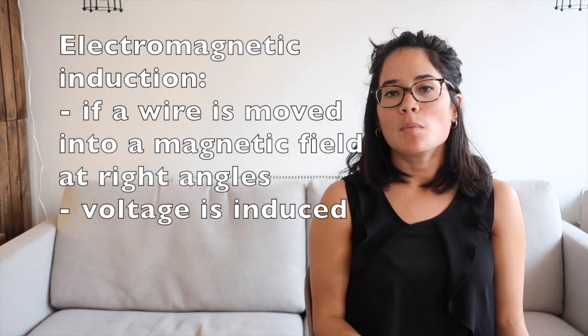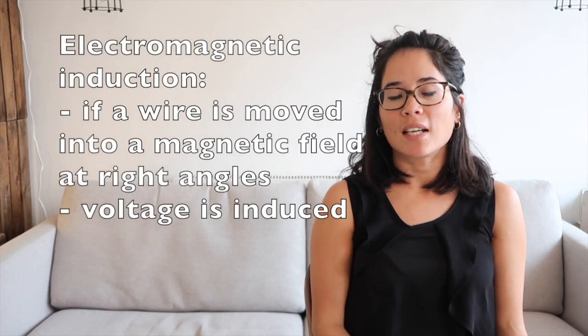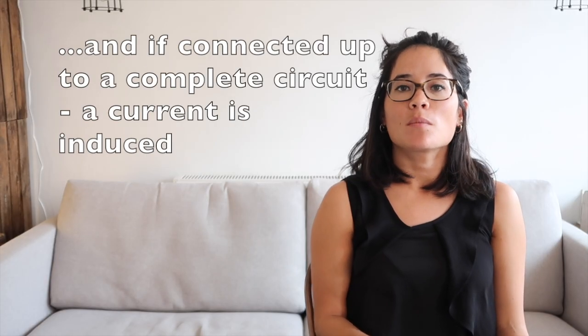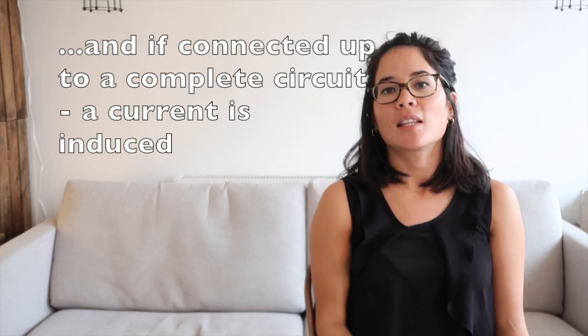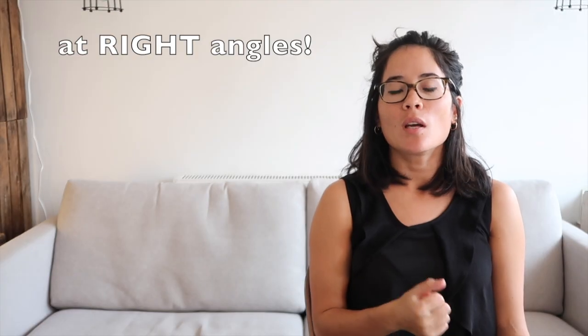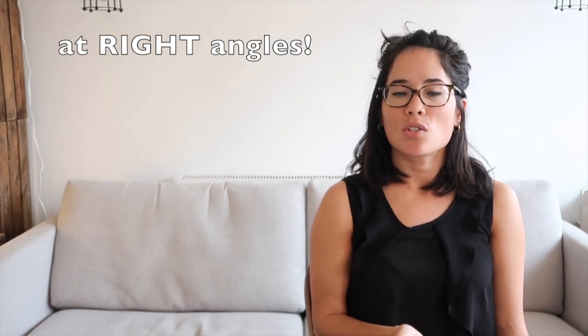If a wire is moved into a magnetic field at right angles, then you find that a voltage will be induced. And if it's connected up to a complete circuit, that's where your current comes from. Do notice that you must move the wire or the magnets, it doesn't matter which way around you do it, but you must move them at 90 degrees to each other.